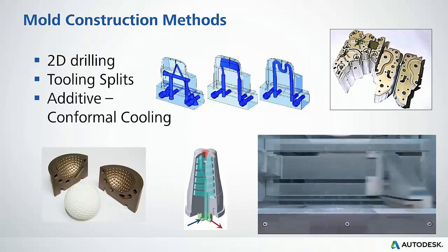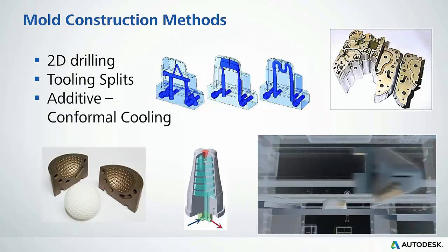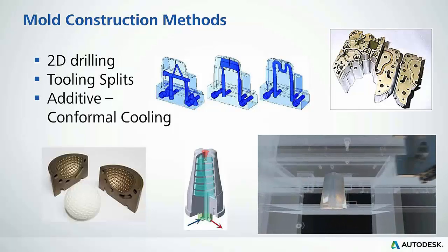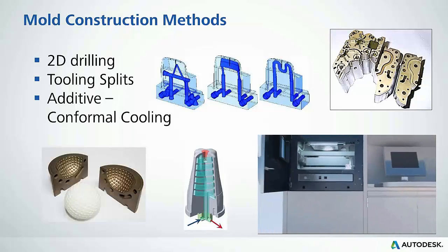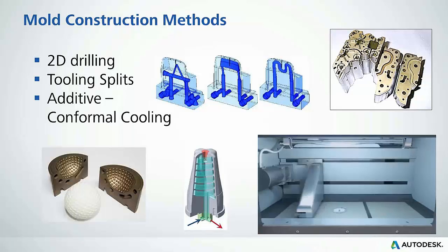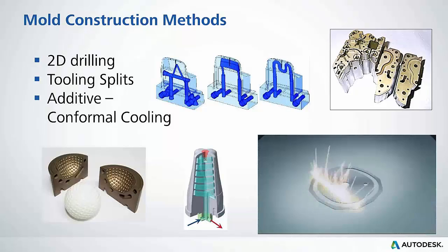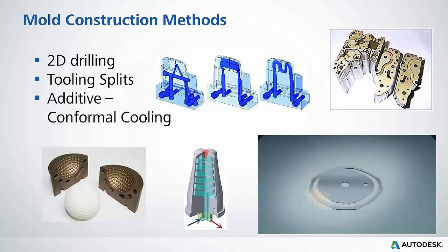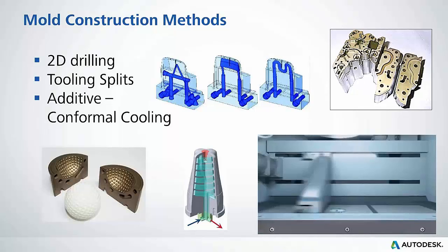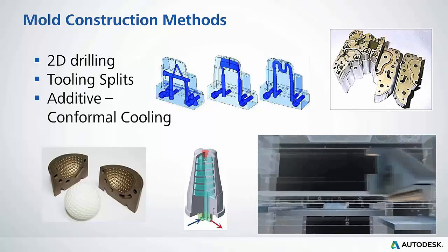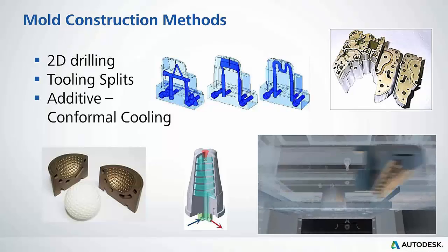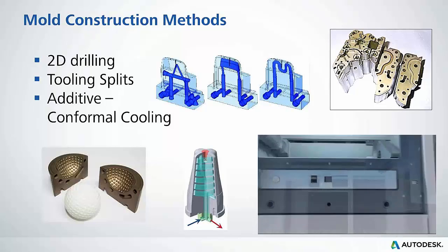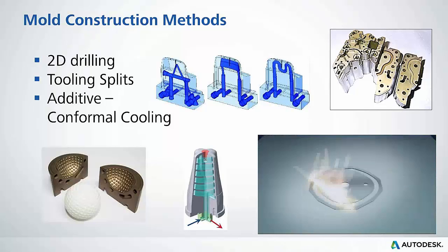So construction methods. It varies. In the old days, we pretty much used a 2D drilling approach, just crisscross applesauce with plugs and ins and outs, series, parallel. We got more complex with our tooling construction methods. We started looking at basically making our tools into jigsaw puzzles and placing O-rings to get cooling in really tight places. So kind of a transition to driving cooling lines, water, to where we need it, where our heat loads are.